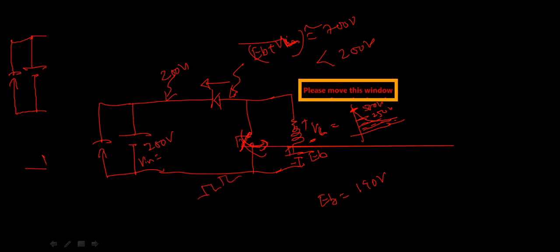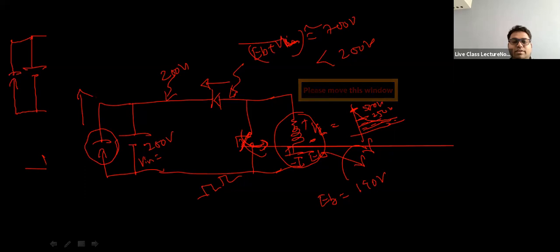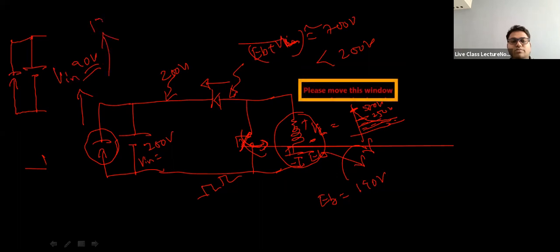Yes. So sometime will come when all the energy of this rotating DC motor will go down to the capacitor, and the capacitor voltage will increase. If you just go to the YouTube video that I had created on the 4-quadrant chopper, you'll find that if the input voltage is, say, 90 volts, the capacitor voltage rose up to 170 or 190 volts. If you have some time, you can check after the class. The voltage of the capacitor was very high then.